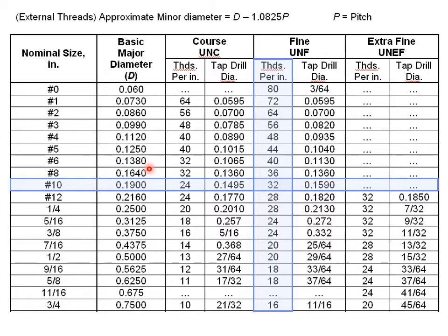Okay, in the back of your book, in the index area, there's this table. And this table is for threads involving inches. I don't have the entire table here. There's some rows missing with larger diameters. Okay, so let's take a look at ½ inch. So if your boss tells you to order ½ inch threads, they're referring to 1/2 is equal to 0.50 inches, and that's your major diameter for the threads. If we order quarter, 1/4, that's 0.25 inches for your major diameter.